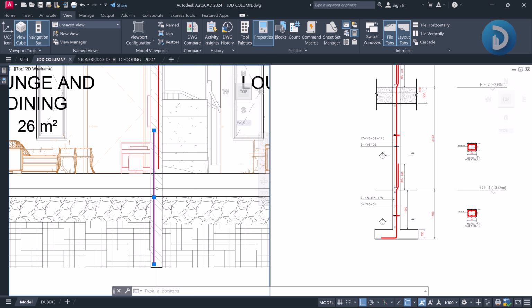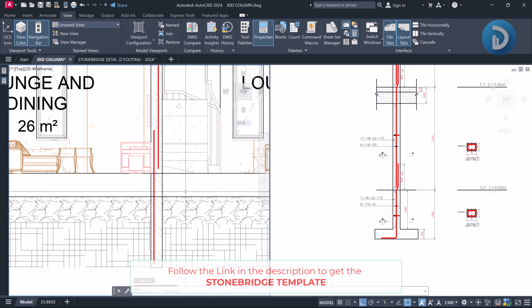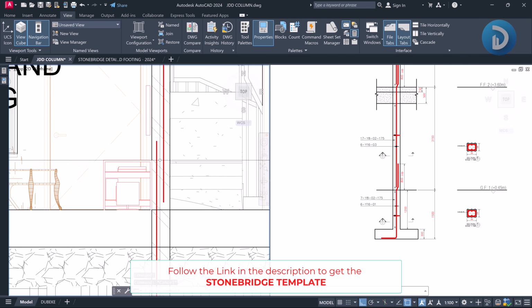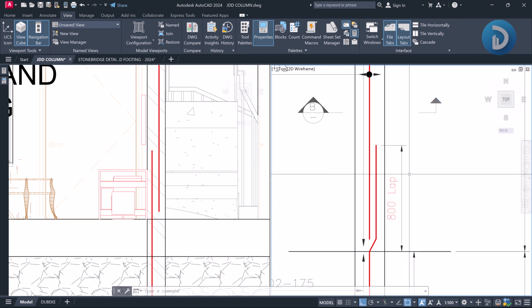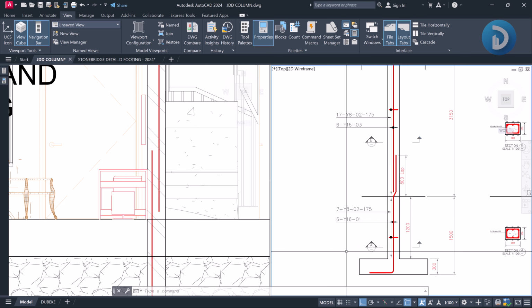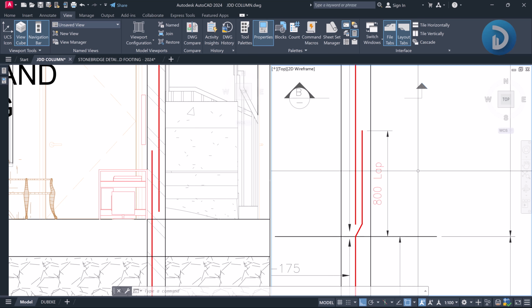You should also have starter bars for other structural members like your staircases. But this is your column starter bars, and it will lap with the reinforcement on the ground floor, and it will lap with your column at the ground floor by a specific length. Okay, and the length of this lap that is required to provide proper anchorage for the reinforcement coming from the foundation level to the ground floor is gotten by multiplying 50 by the diameter of that reinforcement.